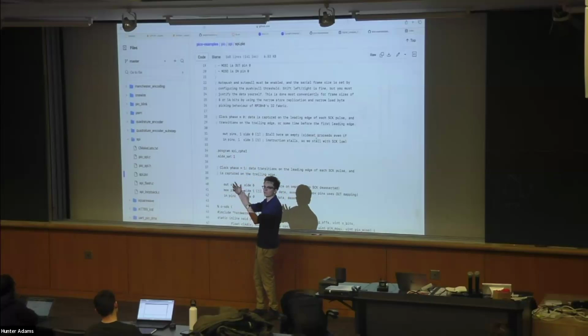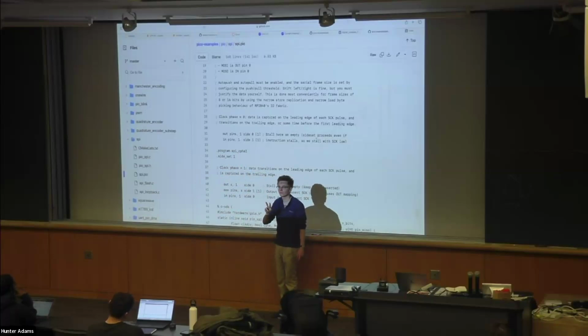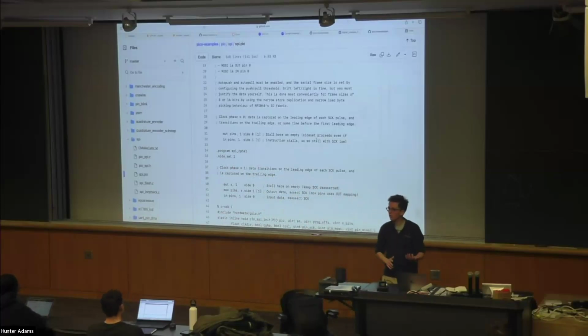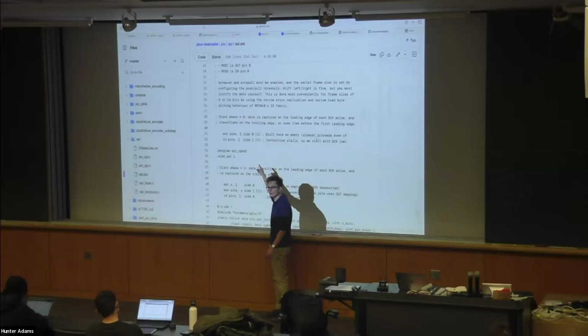Every time it counts up to some threshold, in the case of the DAC, this would be 16 because we're doing 16-bit transactions, it automatically executes a subsequent pull. And in the event that there's no data to pull, it'll stall on that out instruction. And so auto push and auto pull in this example has saved us 2 whole instructions. But that whole protocol in PIO reduces to a 2-line program.